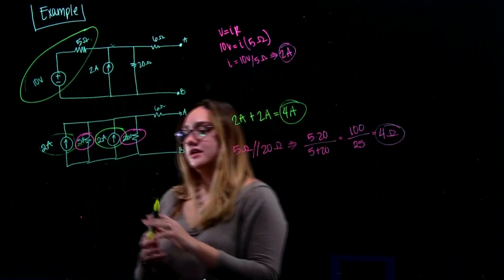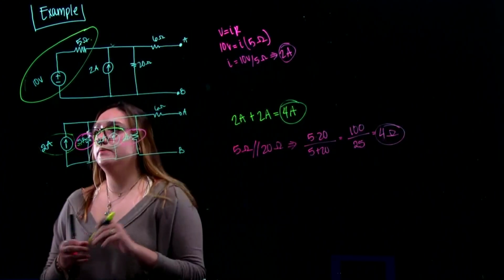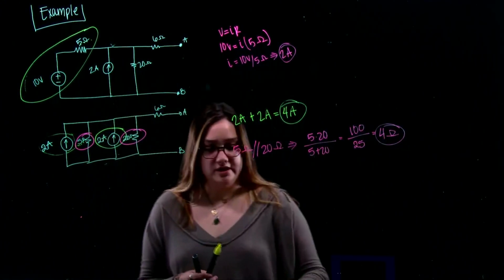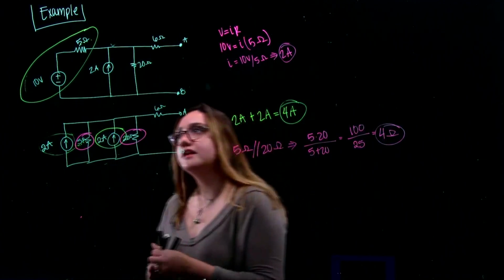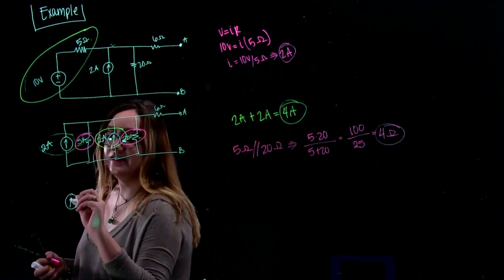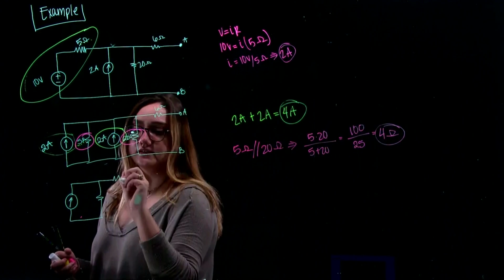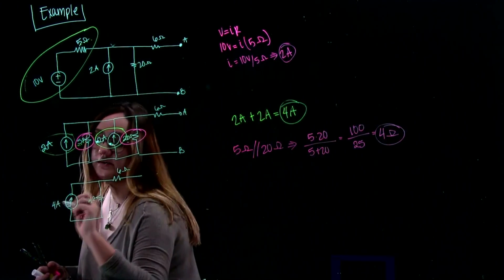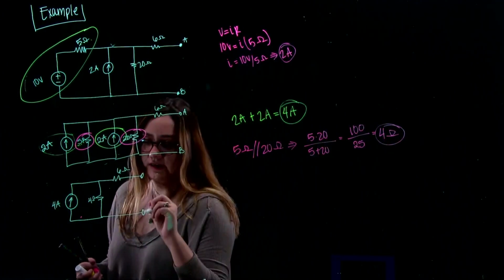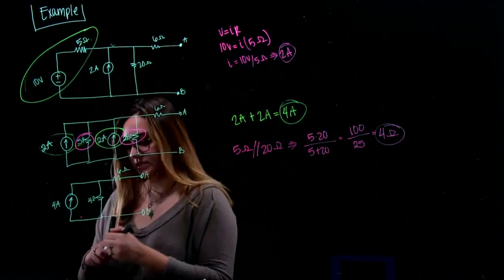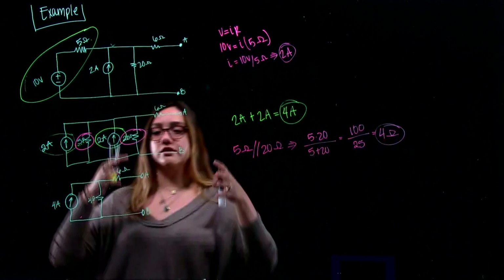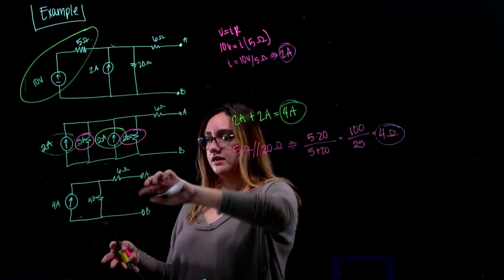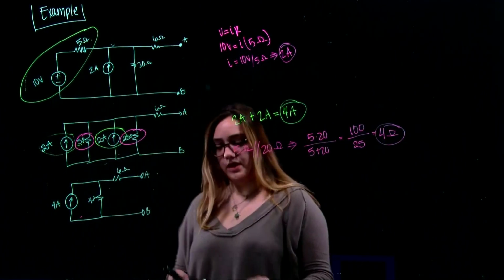So when you take that, you're going to now put it into a new circuit, because we're breaking it down. We're going to make it a lot easier. We're going to make it a 6 ohm resistor at the top, and that will now start playing a part. Because what you're originally trying to find is just a way to break this down into the Norton equivalent, which takes these into consideration, and this plays a huge part as well.